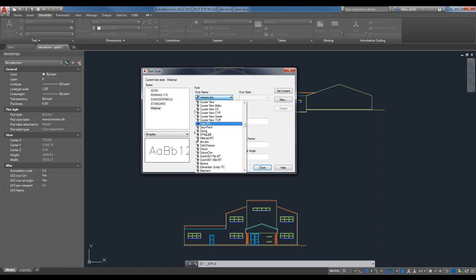So you have this TT symbol, and then you also have a compass symbol. That's because there are two main fonts that AutoCAD uses. You'll have your TrueType font, which is your Windows operating system font installed directly on your operating system. Let me just go to one of the most commonly used ones, Times New Roman, your Comic Sans. That's going to be your TrueType font.